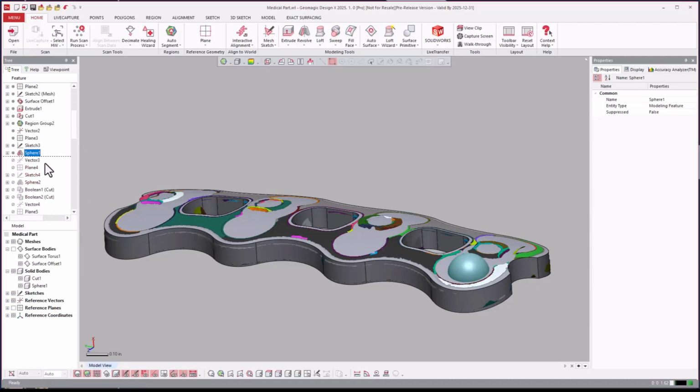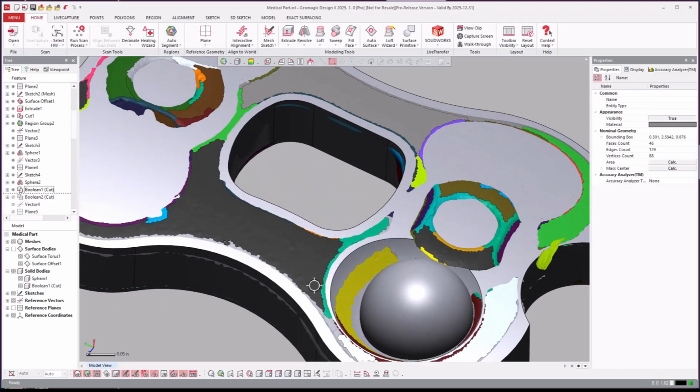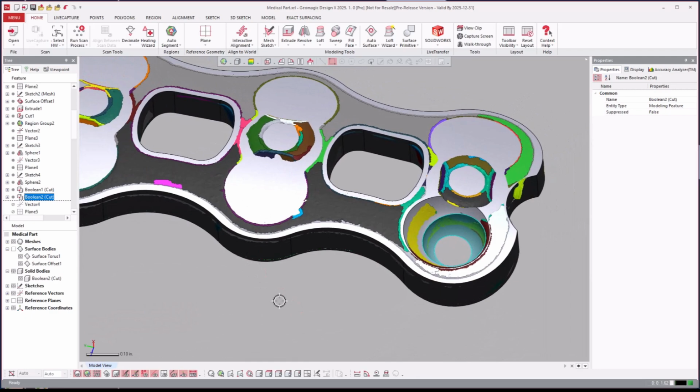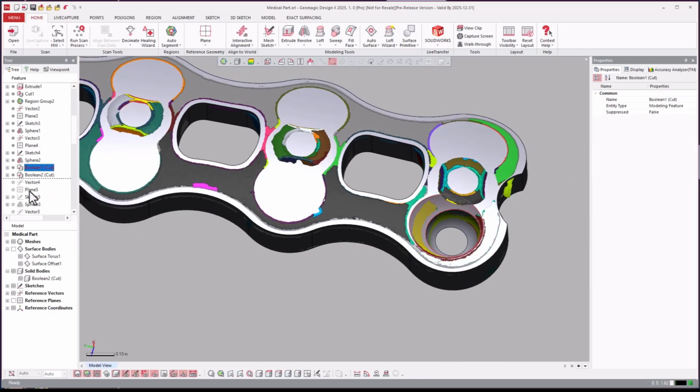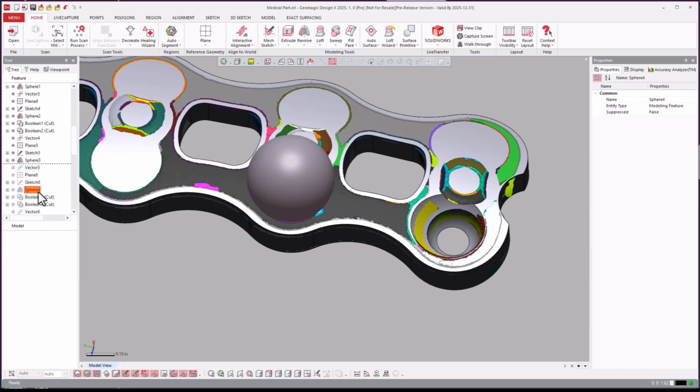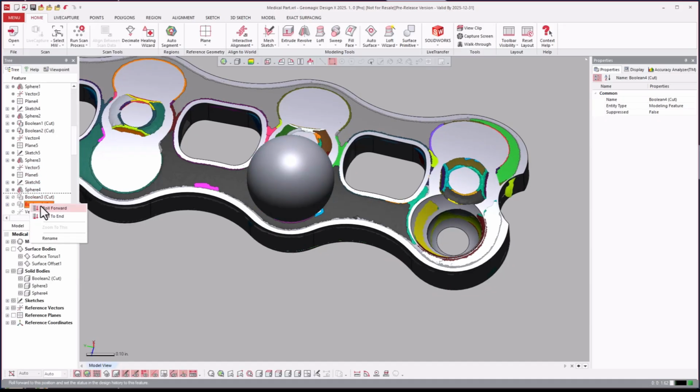They went ahead and extracted a sphere using primitives over here. You can tell by the naming of the revolve. So they went ahead and cut that first one away, cut the second one away, and then they're going to do the same thing here. They're going to fit both of them and then cut them both away.